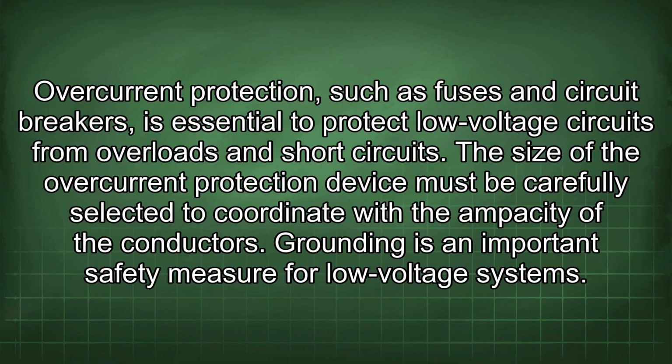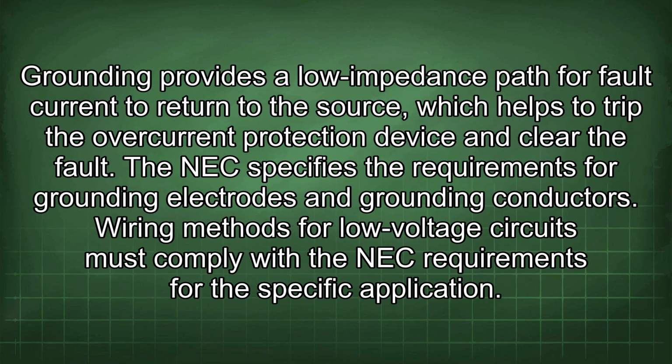conductors. Grounding is an important safety measure for low voltage systems. Grounding provides a low impedance path for fault current to return to the source, which helps to trip the overcurrent protection device and clear the fault. The NEC specifies the requirements for grounding electrodes and grounding conductors.